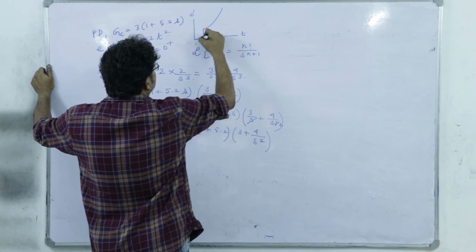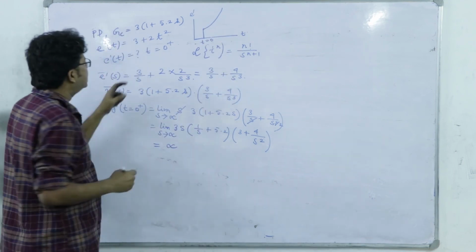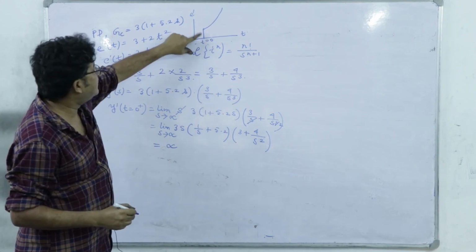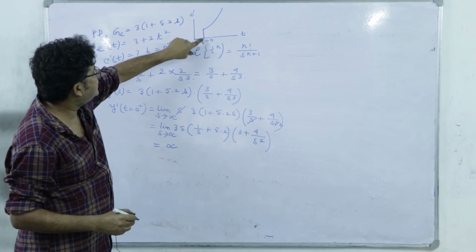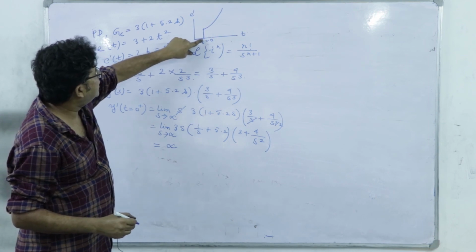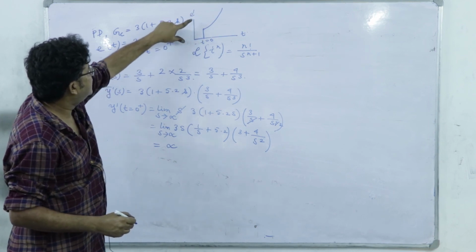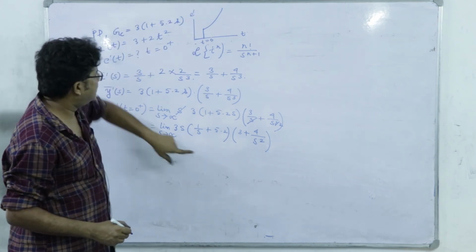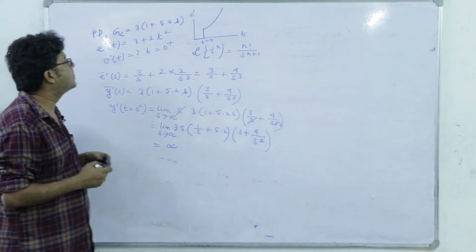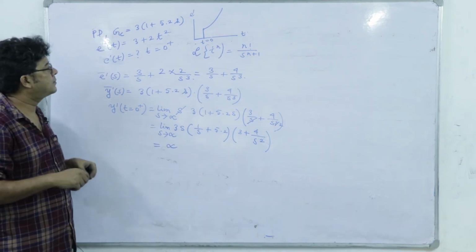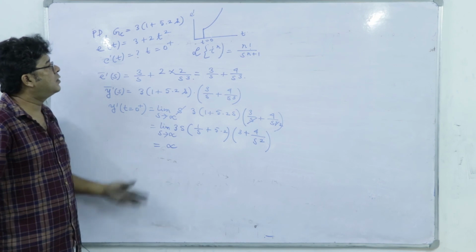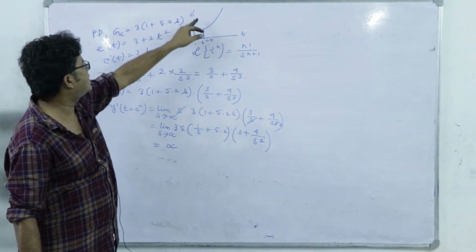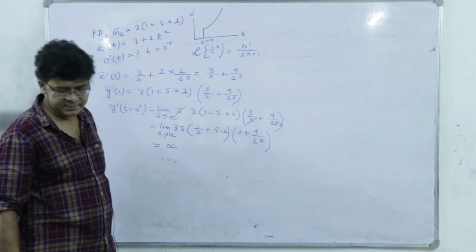And now when it faces this jump, what will the derivative mode encounter? A derivative which is infinity. At t equal to 0 plus, it will have a derivative which is infinity, right. And because of that, it will give you infinity here. Okay. Because the derivative mode jumps to infinity as it faces a hike from 0 to 3.